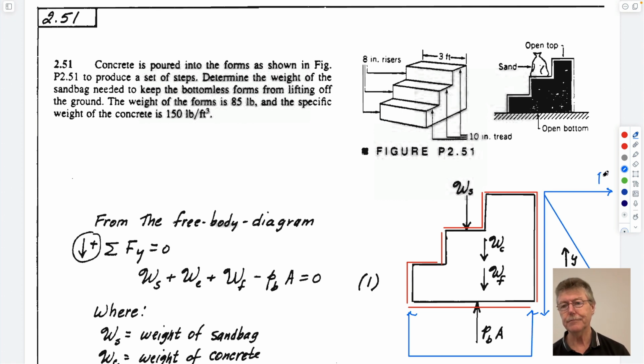So this is Z, right? This is the pressure change with Z. And so if you look at this depth here, this is your H. Then this is going to be PA, right? So we know that PA is equal to P0 plus H times unit weight of concrete. P0 is definitely 0 if you take it as gauge pressure. So you have that magnitude.